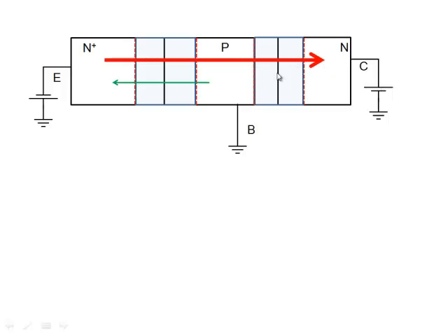Now, this current that flows across this particular junction that you see here, what is it? It's flowing across a reverse bias junction. In a reverse bias junction, is the current dependent on voltage? It doesn't depend on voltage, because what can the voltage do? If you ask yourself, what can this voltage do? It can increase the electric field, right? It can increase the electric field.